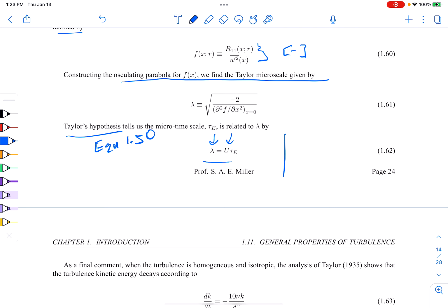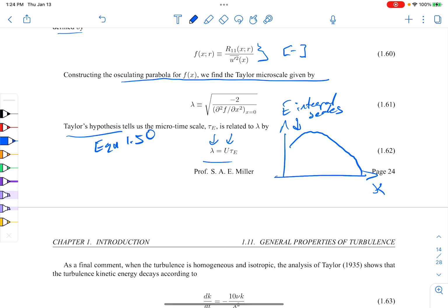And so if we plot the scales in terms of energy in a turbulent flow, first wave number kappa, you should see something like this. Here's the integral scales. And we'll look at this in more detail on Tuesday, excuse me. And here's the smallest scales. This is the location of where Taylor's scales are, the intermediate scales. And usually this is a logarithmic plot, so it's really log of kappa. And there might be many decades or orders of magnitude between the largest scales and the small scales, and we'll try to estimate that.